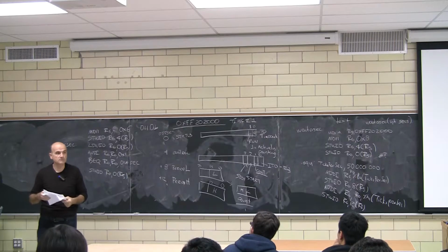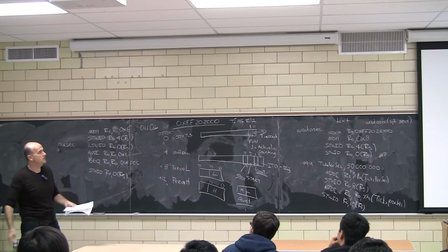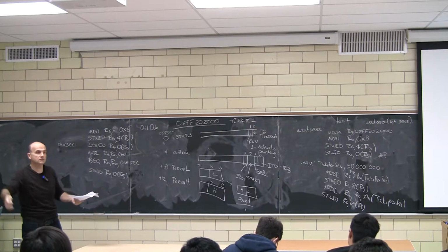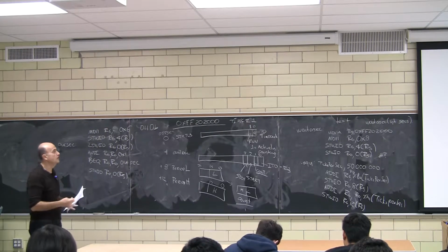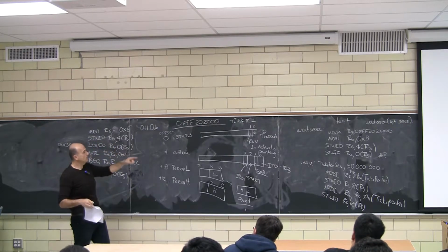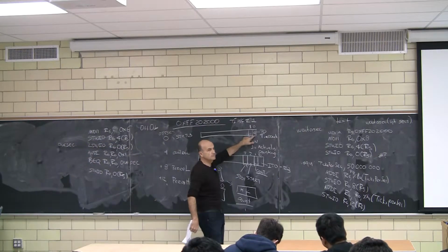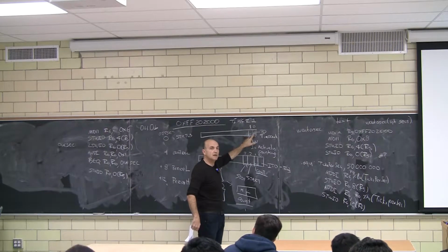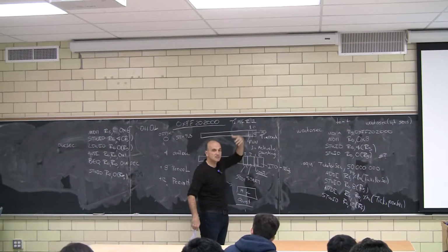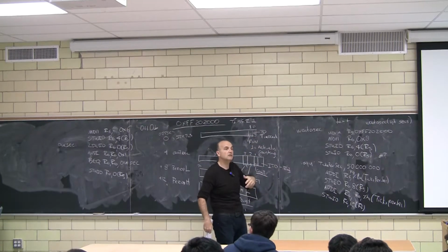So far, so good? In the beginning of time, we started the timer. We said count a second, but do that continuously. So start at 50 million and count down to 0. The counter starts counting, and we go into a busy wait loop. We keep looking at this indicator. The moment that indicator becomes 1, it means the timer has reached 1 second. We clear it because we asked the timer to do this continuously. It's going to count another second now.